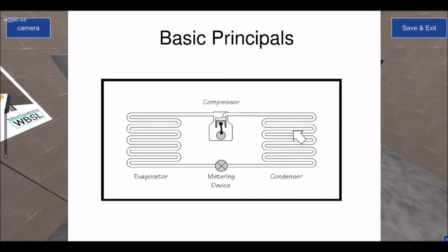So when we're dealing with refrigeration systems, because you've got high side pressure and low side pressure, we're actually changing the boiling temperature of the refrigerant on each side of the system. So the boiling temperature for the refrigerant in this condenser, for example, could be 35 degrees Celsius, and then you would have vapor superheated above that. Anything above 35 degrees Celsius is superheated vapor. Whereas on this side of the system, it could be as low as 5 degrees Celsius, again relating to the pressure-temperature relationship.